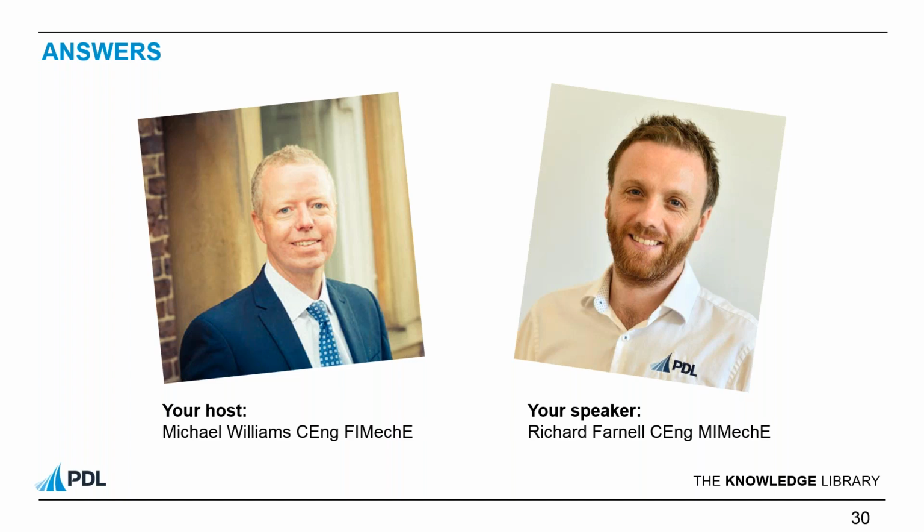In lieu of that, if you don't have that information, then synthetic curves are available to be developed. So if you're following ASME Division 2, I think there's a methodology stated in Annex 3D, and somewhere in KD 231 is the method for developing the same curves for ASME VIII Division 3. I think they're both comparable and they essentially produce the same curve though.